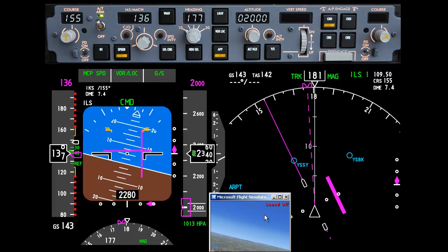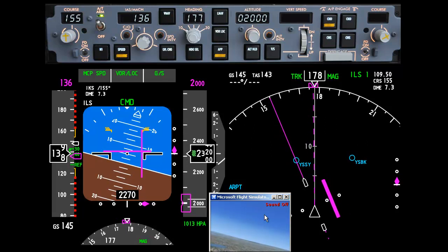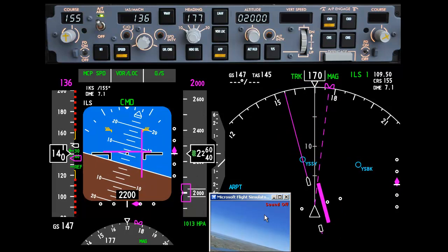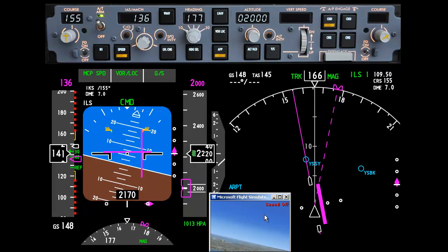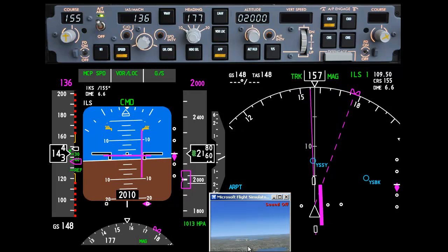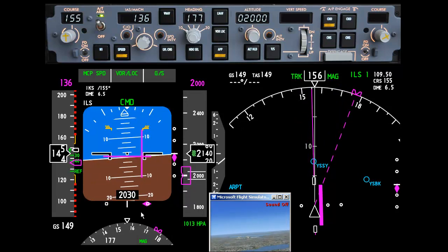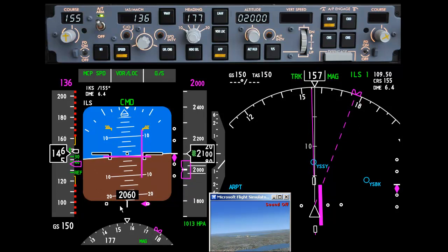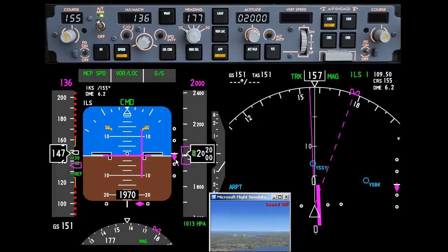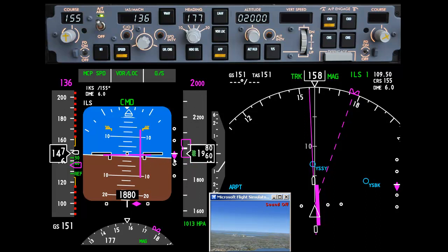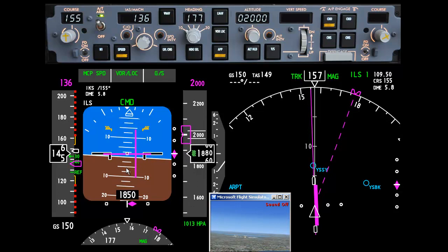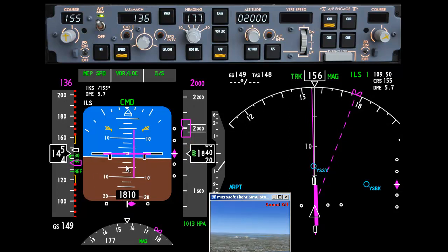As I mentioned before, I'm not using the autopilot in Flight Sim at all, except for altitude. So these routines here are the software flying the aeroplane simply by using the ailerons. You can see Sydney in the distance, and on the primary flight display, we've almost intercepted the localizer. The aeroplane is now descending to intercept the glide slope, and the magenta flight director bar is coming to the center of the display to show us that we're almost on the ILS.